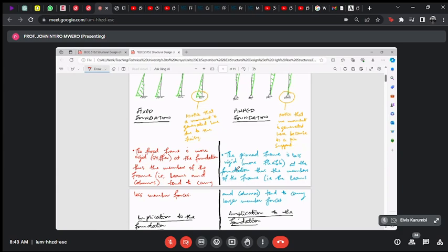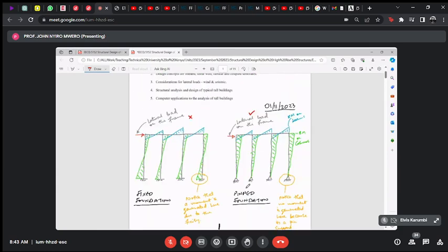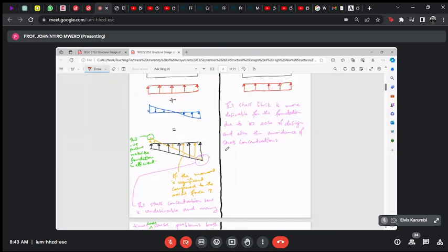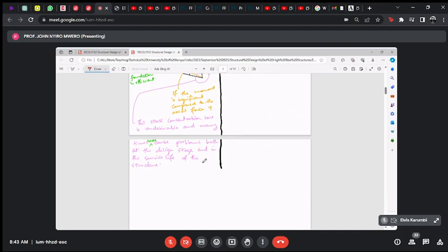Many designers prefer to just make it pinned. That way you have a slightly heavier structure, so you design and provide for that, as opposed to having to design for this and deal with the extra effort of dealing with the stress concentrations.